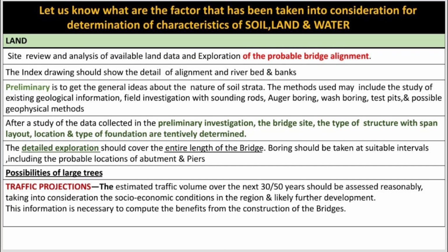Since in most cases COS is part and parcel of the existing contractor, this becomes a point of conflict also. It has financial implications. It increases the cost of the project. And secondly, on the basis of change of scope, the contractor claims an extension of time. The EOT on the basis of change of scope protects the contractors from the penalty if their progress is slow in the original contract. So one needs to be very careful in providing change of scope to the contractor.